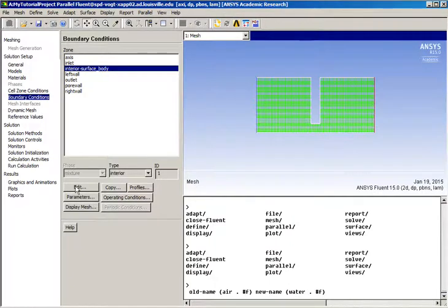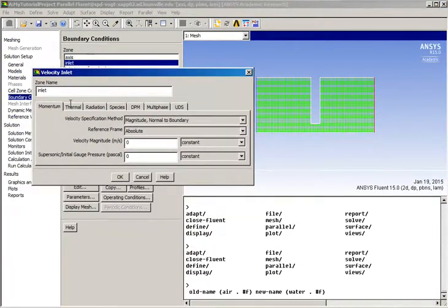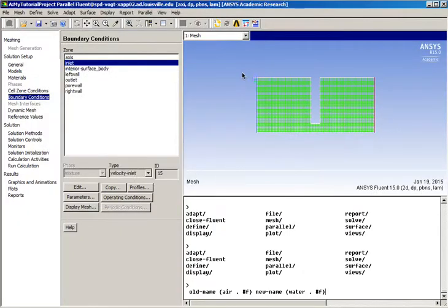We can look at some of the other ones. That's the green stuff. Let's look at the inlet. Just to be clear, the inlet is not moving. There's no velocity on the inlet wall. And that's kind of unusual, but it is representing a closed container. Usually people will have an inlet flow that's coming from maybe some other simulation or just some conditions that they want to set up in a wind tunnel or something. Okay, and then so I can move on down.